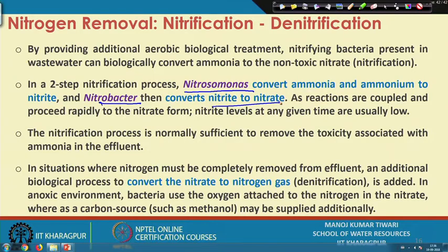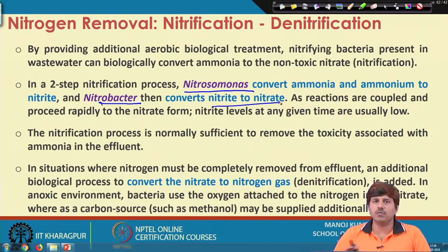The nitrification process is normally sufficient to remove the toxicity associated with the ammonia in the effluent. So, for several purposes where we are just bothered about the toxicity, we may not even need any additional step. Just nitrification is good enough because ammonia has been converted to nitrate, and then we release it, or we reuse it as a nutrient, because nitrate is used in fertilizers and those kinds of things.